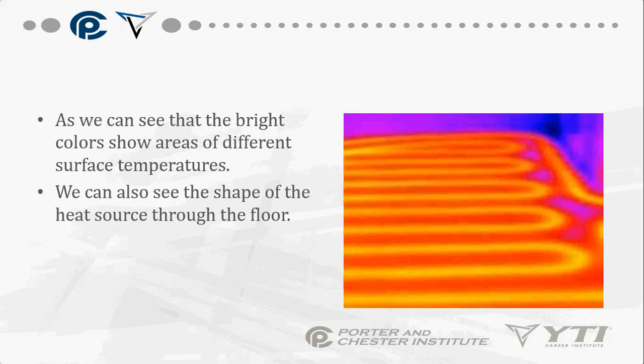It does not have to be an extravagant thousands-of-dollars thermal imaging camera. You can get something relatively cheap, maybe a few hundred dollars, and you can honestly take thermal imaging temperature readings to see where you have hot and cold spots in your baseboard or even in your radiant heat applications.